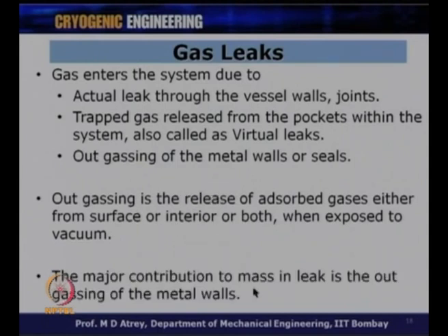The major contribution to the mass in leak is the outgassing. So, out of all these parameters, outgassing is a very important parameter that has to be considered. The contribution from outgassing is going to be a major contribution to mass in leak, and that's why it has to be considered correctly while designing a particular vacuum system.